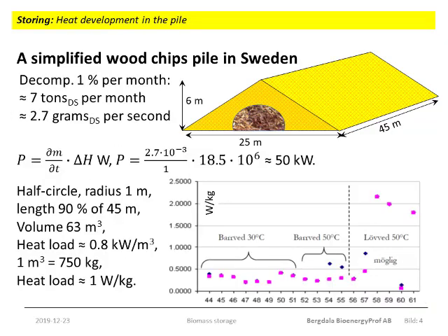As you see from the slide, the total breakdown ratio is about 2.5 to 3 grams per second. And the dry substance has a heating value about 18 to 19 megajoules per kilo. And then the rate corresponds to about 45 to 55 kilowatts.